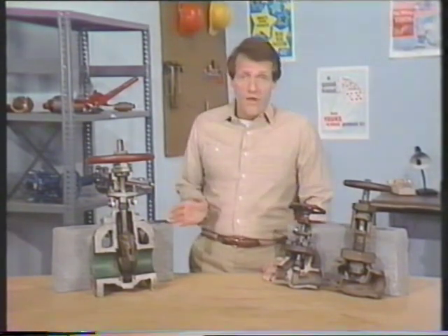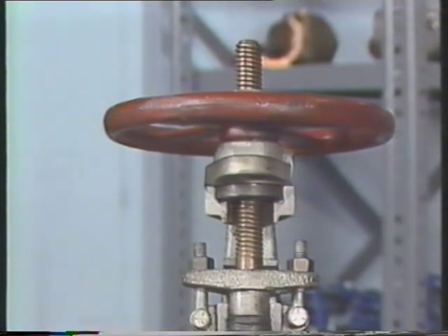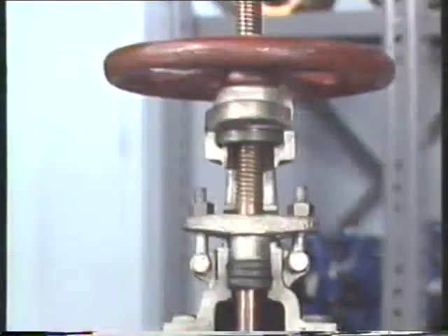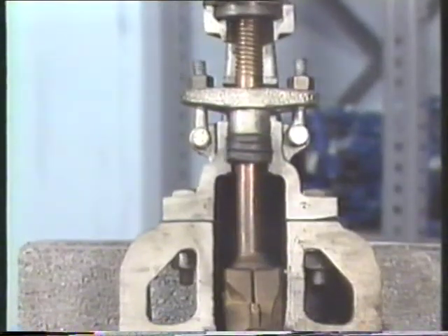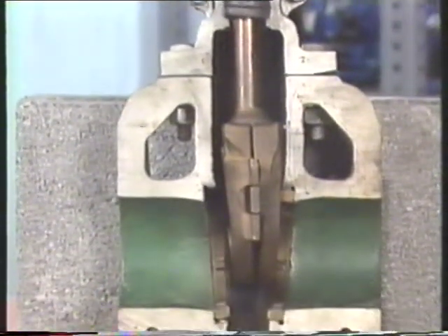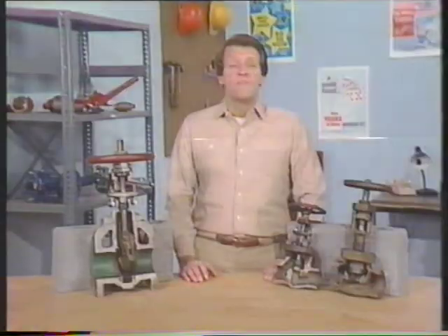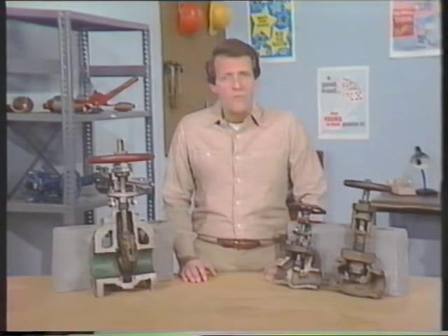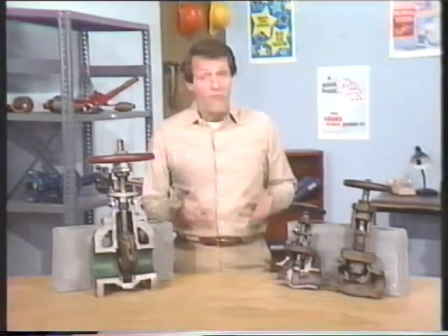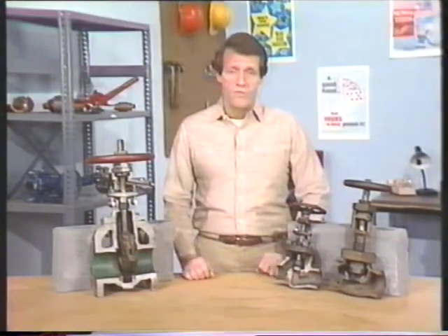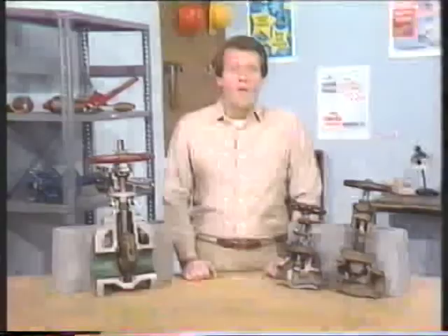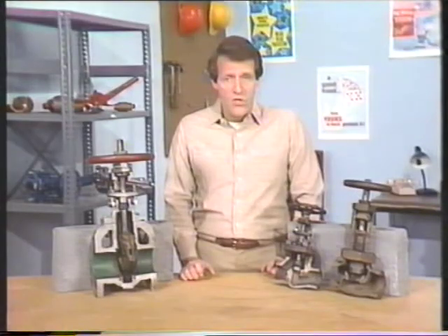This is a cutaway of one. Generally, a gate valve can be identified by its relatively long body and stem that extends some distance beyond the piping to which it's connected. Gate valves are primarily designed to be used for on-off purposes. In other words, they operate best in either the fully open or fully closed position. However, a gate valve may be used for throttling in an emergency.